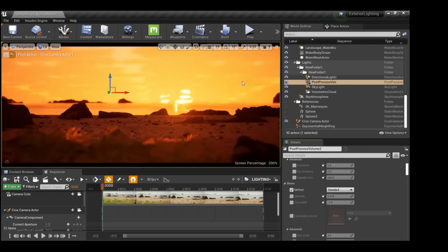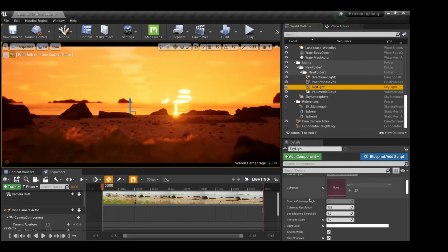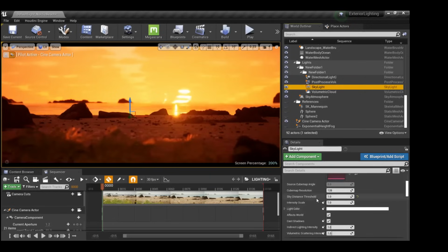Okay, thank you. Just one thing, in the skylight, the distance you kept right now was more than 15,000. So what happens if we keep that by default? Then it will not give the nearest object reflection. Totally right.